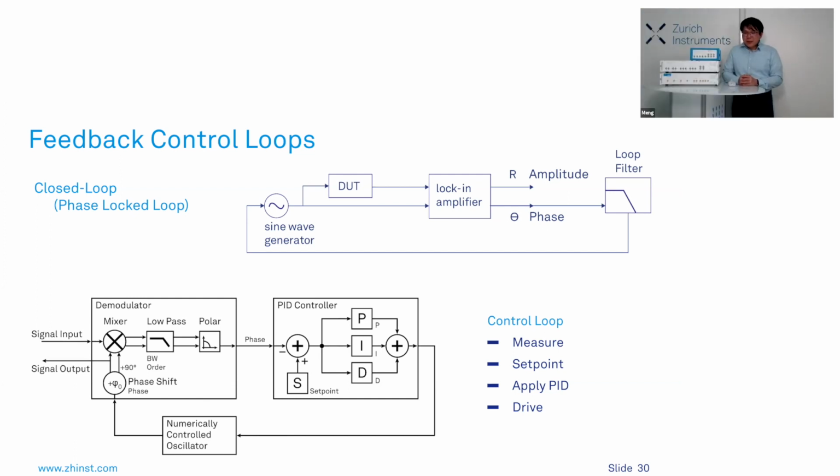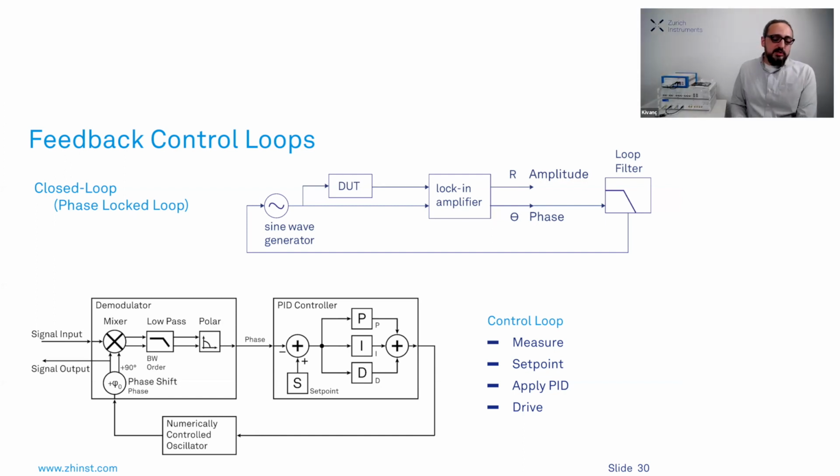And a more specific question about MFLI control, and you are our expert. I believe you can give a great answer to that. A user asked, for example, is it possible to feed, let's say, the output of PLL or PID1 into the input of the second PID and use, for example, auxiliary voltage to control the resonance frequency somehow? You can do these things, yes. We also have auxiliary output channels in the instruments. What you can do is route the PID output to these auxiliary channels. And then you can use these auxiliary channels again to do the lock-in measurement as well.